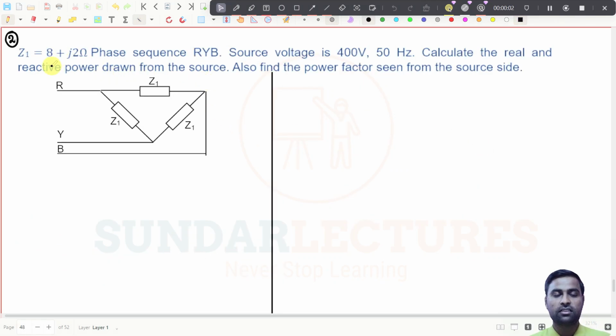This is the second problem. They have given you Z1 as 8 plus j2 ohms. Phase sequence is RYB. Source voltage is 400 volt, that means the voltage between two lines. If they have given it like this, you should assume these are line voltages. And 50 Hz. Calculate the real and reactive power drawn from the source. Also find the power factor seen from the source side.